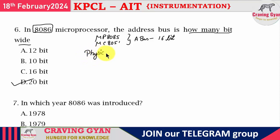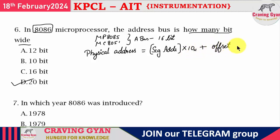In the case of 8086, the physical address is calculated with the help of segment registers. We have 4 segments: data segment, code segment, stack segment and extra segment. Here you make use of the segment register value multiplied by 10H, or 16 in decimal, plus an offset register such as SI, DI, BP, and this is extended to 20 bits wide.